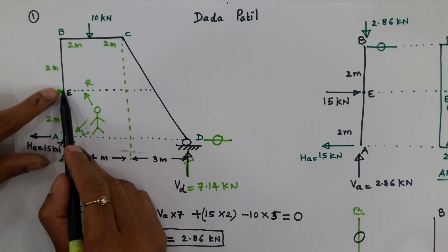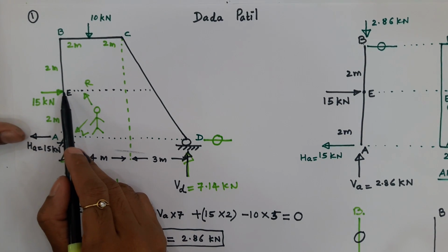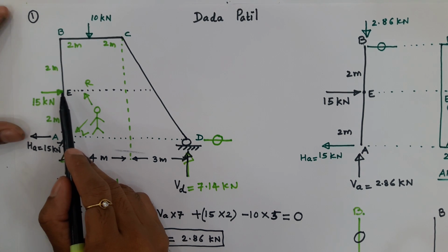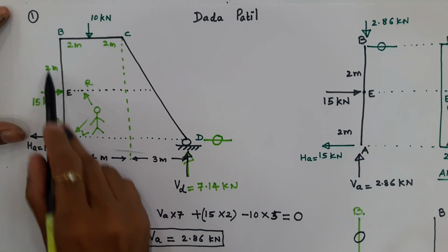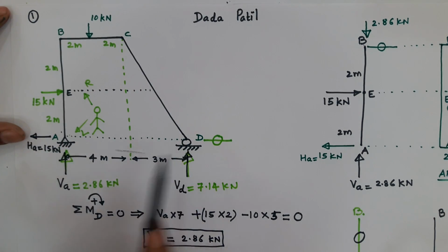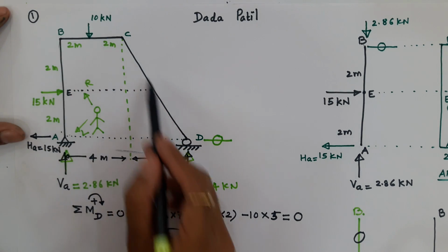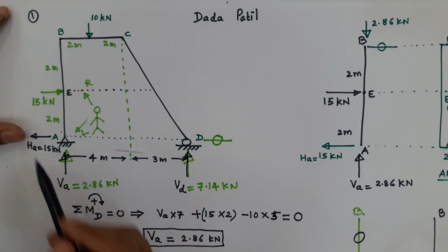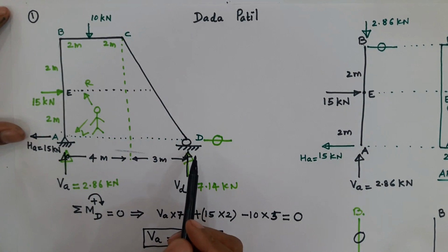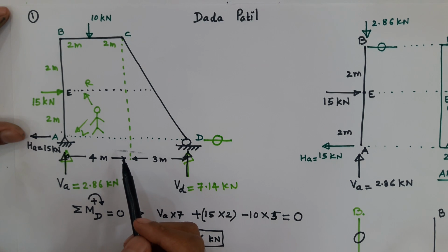What is the definition of bending moment? The definition of bending moment is, it is a moment which is trying to bend that element, and it is obtained as the algebraic summation of moments of all the forces including reactions either lying on one part or on the other part of the structure. So the other part is somewhat complicated. It's not actually complicated but somewhat time consuming.